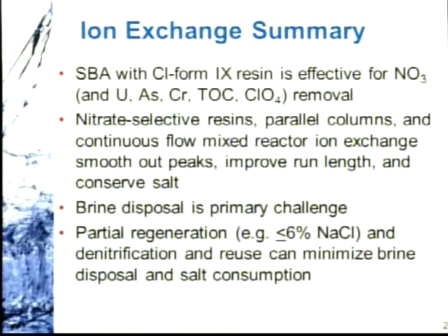So in summary, strong base anion exchange is certainly a technology that can be used well for nitrate. Because nitrate is not as selective as the other contaminants listed here (uranium was mentioned earlier, chrome-6 has been mentioned, arsenic has been mentioned), if you operate a strong base anion exchange resin to remove nitrate, you are going to get removal of all of those other co-occurring contaminants if they're present in the water. So, for example, whereas reverse osmosis systems have the advantage of decreasing the TDS, which is a good aesthetic benefit, this approach has the public health benefit of reducing exposure to those other contaminants if they happen to be present and of concern.